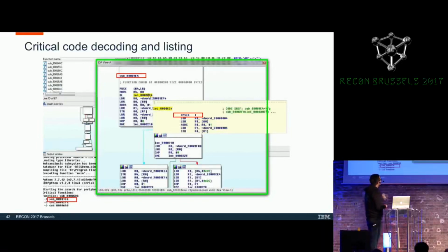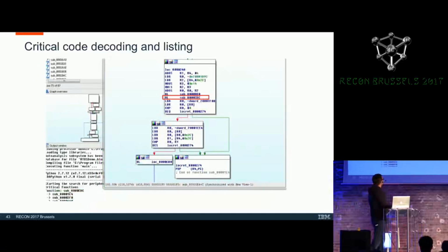This helps us to understand that in this case, for instance, the function 1E4 disables the interrupts right at the beginning of its execution, and then it will re-enable them really down in the code. So if we wanted to understand exactly what that block of code was doing, the good thing would be to try to understand exactly what was going on within that block. Here, it's the same function, but you'll see that we are calling the CDC, which we identified as being one of the functions that has the code to re-enable the interrupts.